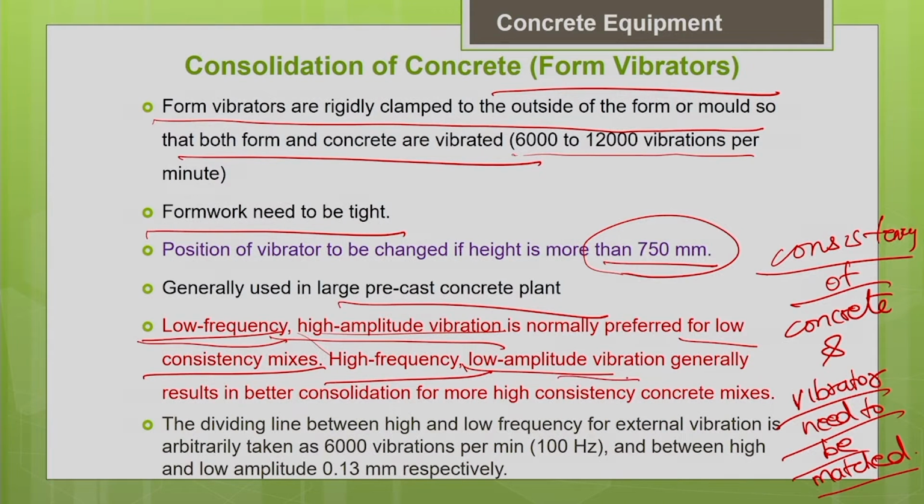So, these are the general guidelines to match the vibrator with the consistency of the concrete. For stiff mixes, better go for higher amplitude and low frequency, and for high consistency mixes, go for lower amplitude and high frequency. This high and low frequency I have just discussed qualitatively.